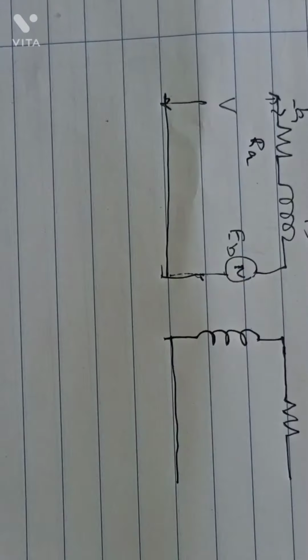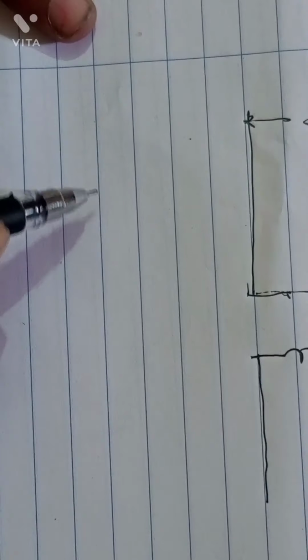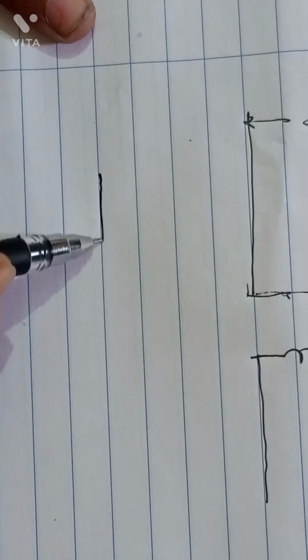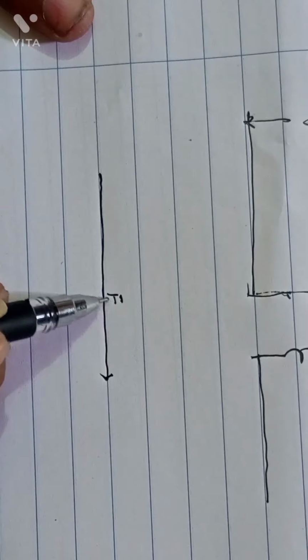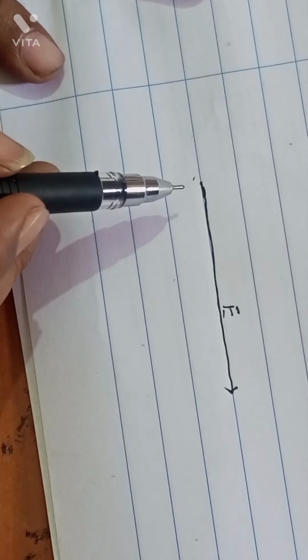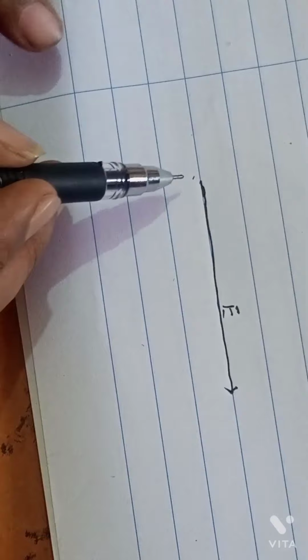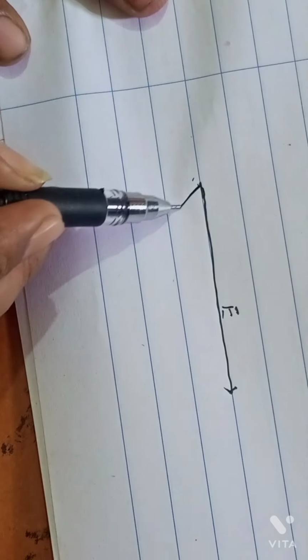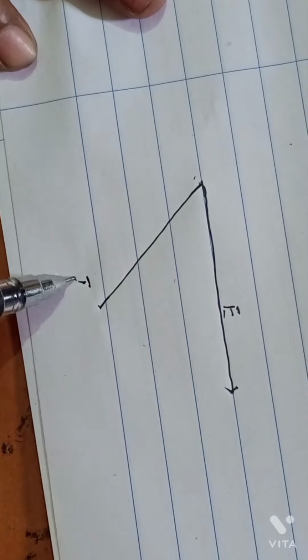Now we draw the phasor diagram. First, E. Take this as E. That is the applied voltage. Then it is the inductors, no? Resistance is negligible. So a motor has a lot of inductance, right? So here I have a current. The current is lagging. It is IA.